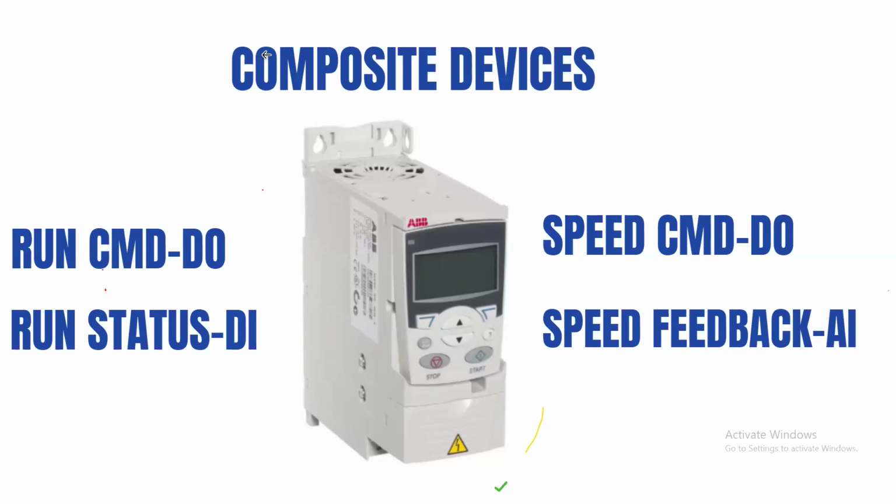Is there a way I can integrate a feedback, so that when I'm not on the field, based on the feedback I'm having on the SCADA, I can definitely and accurately tell that yes, this motor is on? Is there a way I can program or wire a feedback of a contactor to tell me that on the field this motor is actually on and I'm not getting a false signal?